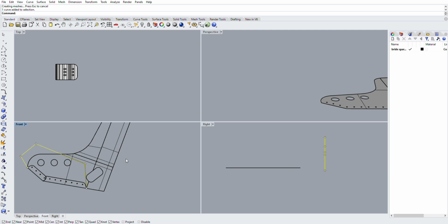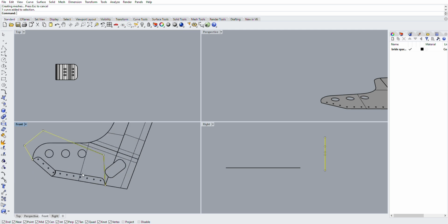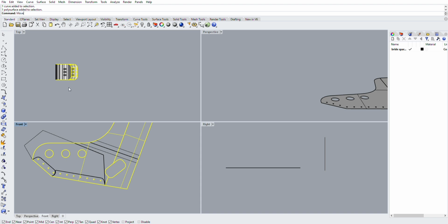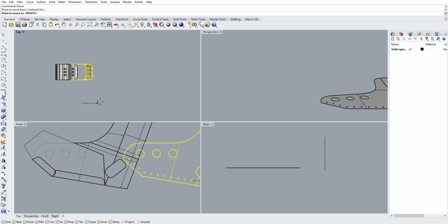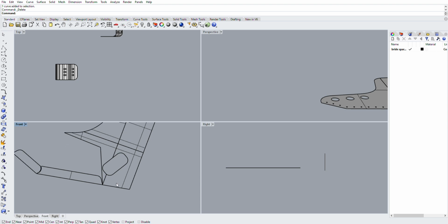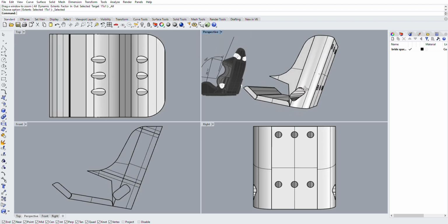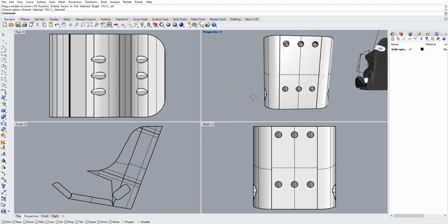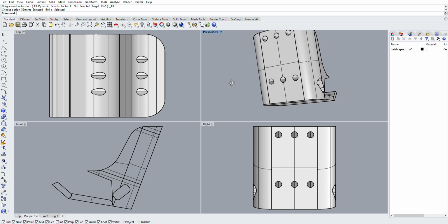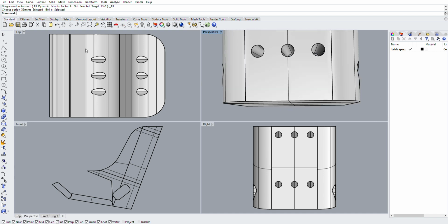It looks a little bit off right now because I've still got the seat back on top of the seat base. So I've got 2 solids taking up space here. So all I'm going to do is move it out of the way. I usually use round numbers, move it 50 back, 50 over. That gets me out of the way in the front view or the back view, the side view, whatever. That means it's not in line on the straight on views that I'm using. And you can see where my flanges stick up there. Now thinking back to the other seat, how I removed everything, just take a moment, you can envision how once I explode this, it's going to leave me with flanges. But I obviously need to do the same thing to the back now as well.